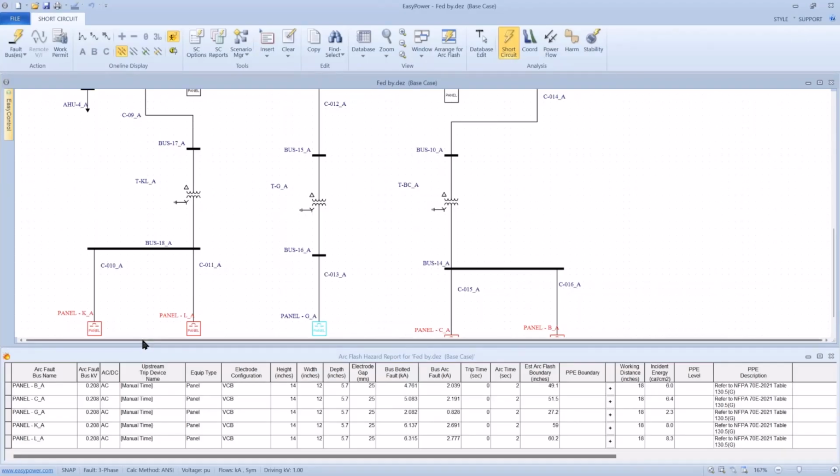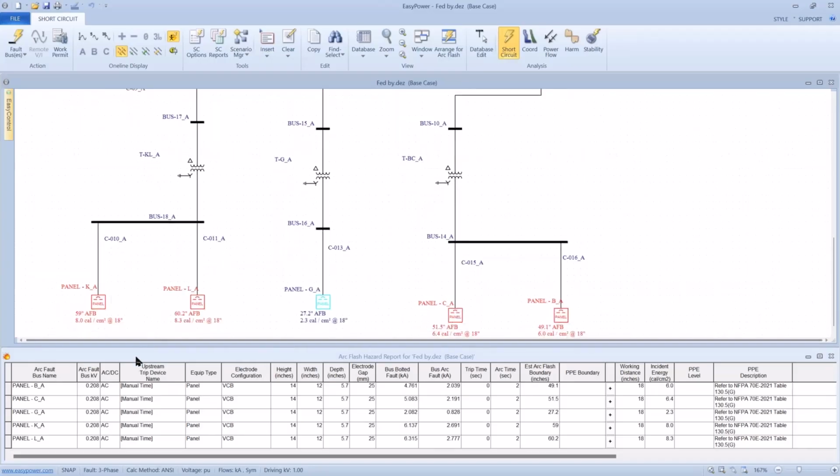This brings up another question, and something to think about if you're a label editor. The manual time, the 2 second max, is for arc flash calculations, so you don't get an indication of which breaker is going to trip as long as it's being interrupted at 2 seconds. But when we're talking about protection for somebody working on this bus, they're not subject to the arc flash limitations for protective devices.